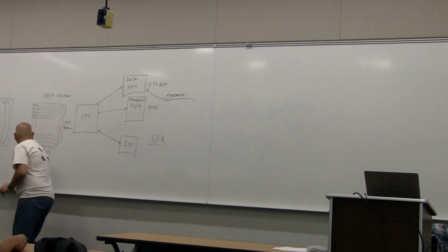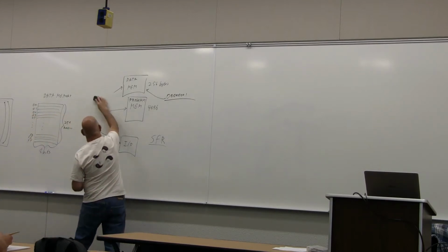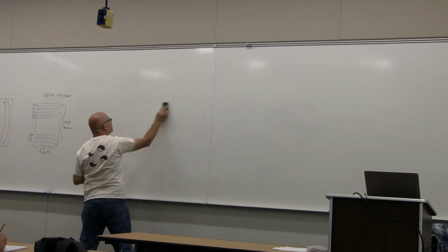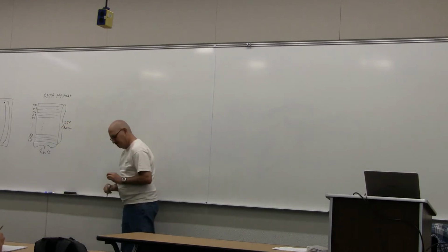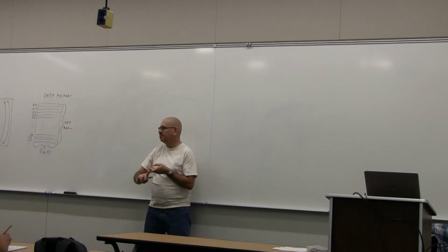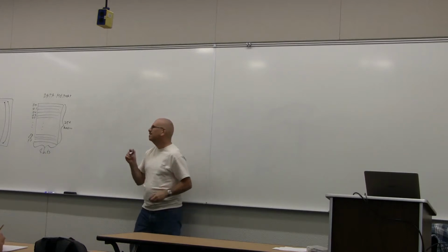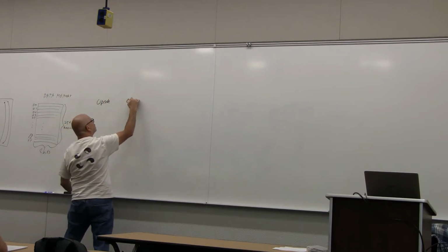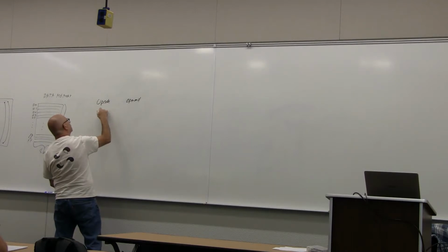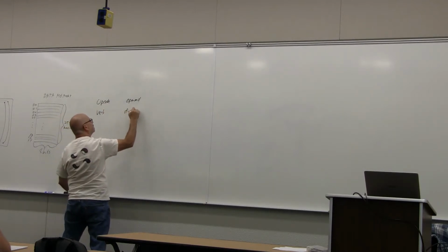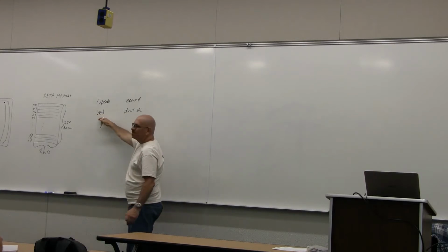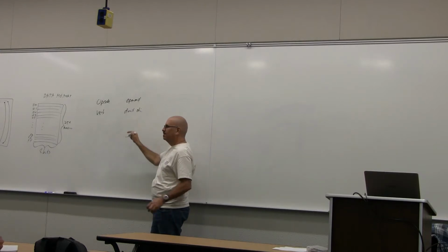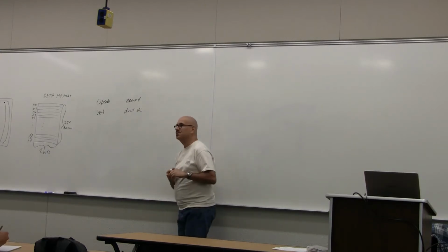So when we're writing a command for the PIC chip, when we're asking it to do something, there's usually 2 things we need to specify. Basically a verb and a direct object. So an opcode and an operand. This is a verb, this is a direct object. This is what we want the computer to do, this is what we want it to do it to. And that's what most of our instructions look like.